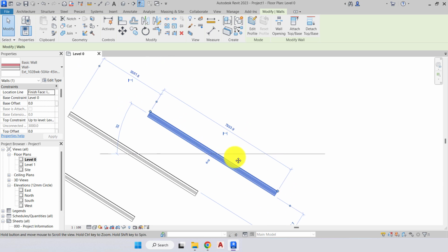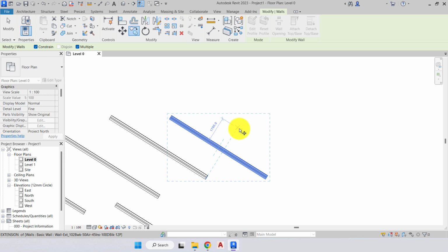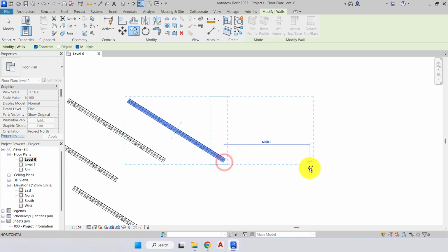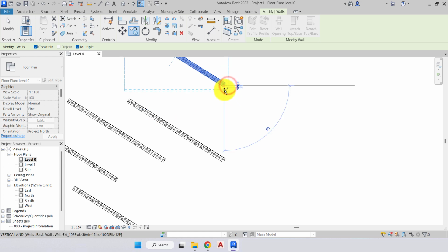Again, coming back, selecting the wall in the copy command. Next, we have constrain. So when we turn constrain on and we move, we can only go at 0 degrees or 90 degrees. This essentially is our ortho mode in AutoCAD. So we can only go 0 and 90.